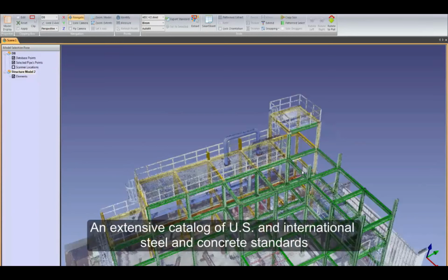We can position our laser scanner on a known point. Then in the laser scan, we can specify the exact coordinates of this point. Then the scanner will automatically do a laser scan, and all the results will be georeferenced. There are some other laser scanners on the market that don't have this feature.